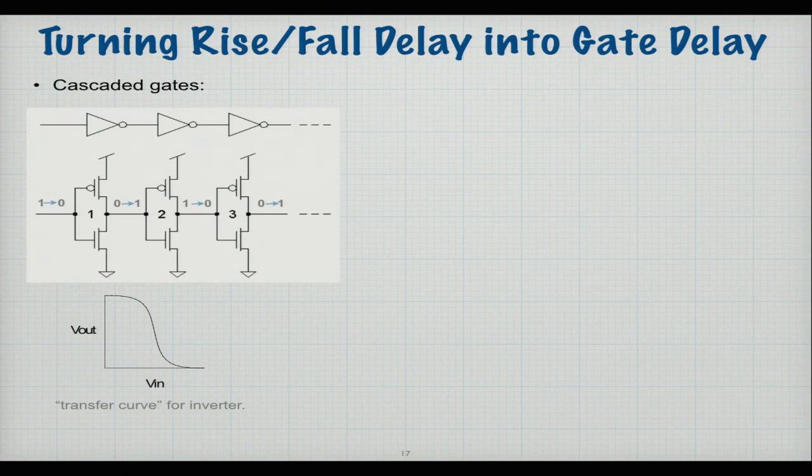And that's a nice property also about CMOS. And that's because the dependence of the input on the output is pretty nonlinear. So once you get about halfway, nothing happens before halfway, once you get past halfway, the output is changed. So they act kind of independently of one another, and you can just kind of add together all their delays.